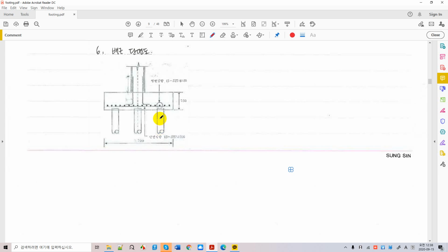If you can have 25 tons easily at a shorter length, then you can stop, right. So the length of piles really depends on soil conditions. You can go deeper and deeper and still not have 25 tons, whereas you can go shorter and shorter and you can get 25 tons per pile. It depends on your soil.